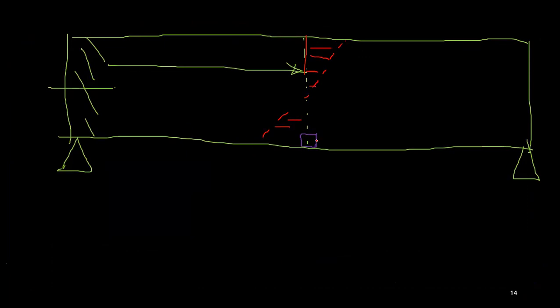So it will have a tensile stress, no shear. It won't have any stress on its surface as well, and doesn't have any normal loading. It doesn't have any complementary shear because this element should be in equilibrium. So this element has only tensile stresses.